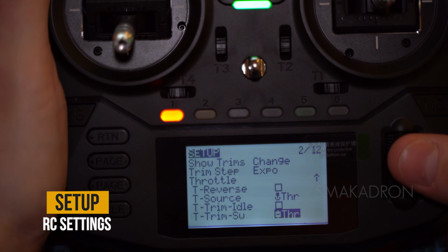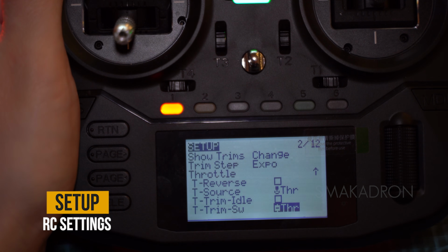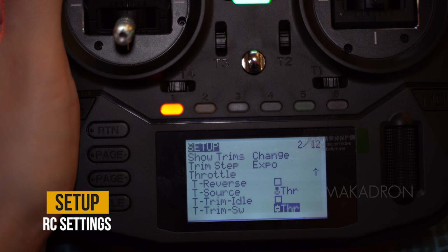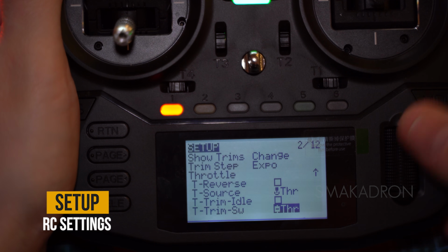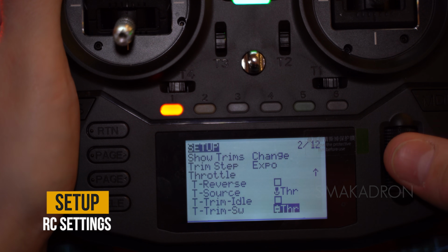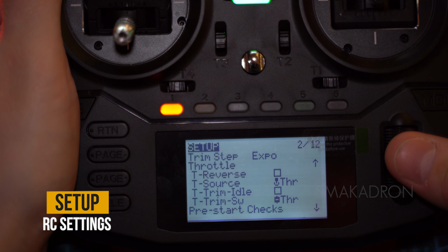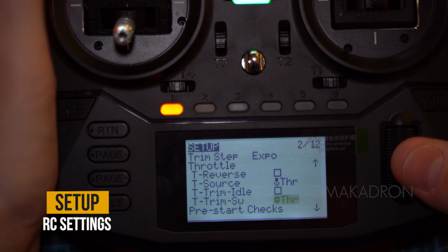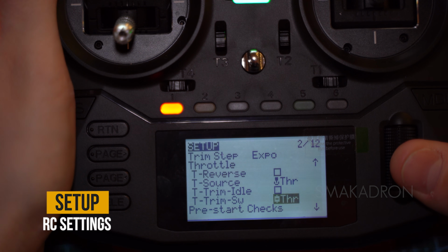Trim switch. Using a trim switch, you can precisely adjust the position of channels like ailerons, elevator, rudder, or throttle for optimal flight. Setting up a switch allows you to quickly change trims during flight without being distracted from controlling the model. You can choose which specific switch will be used for trim adjustments. This allows you to configure the radio transmitter to your personal preferences and habits.